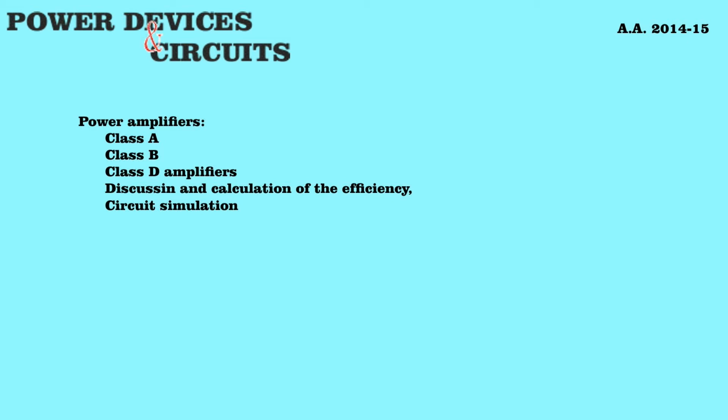The power dissipation will be the on-state voltage drop, multiplied by the on-state current, and this must also be multiplied by the period of time that the device is on in an entire period, that is the on time divided by the period.